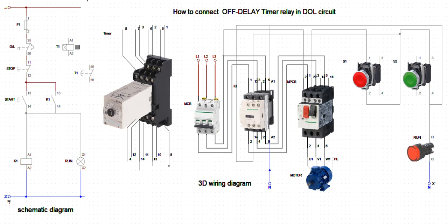Okay. Now let's also activate the wiring. I put it on from this button. Sorry, I energize my circuit breaker. I put it on here. Look at my indicator lamp is on. My contactor is closed. I want to shut down, I shut down from here. Watch this one close when I energize. Okay, this is contactor closing. This is my indicator lamp. Now the pump is running, supposing. Okay, if I shut down here, I shut down.